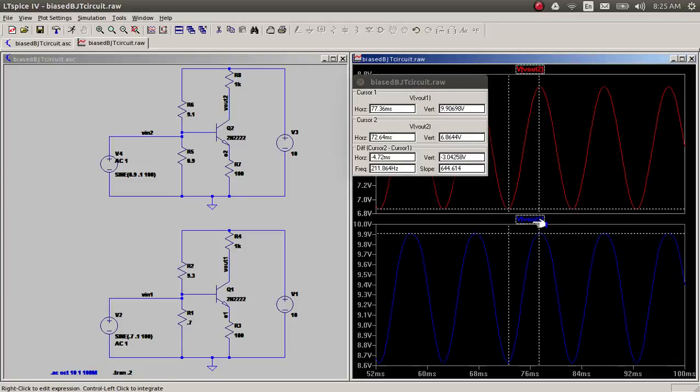And if I look at this one, then this is 1.27, so similar to what we had got before. 0.6 volts is what we are getting at the output for the 60 odd millivolts that we had at the input. So the scaling is fine in both cases, it comes up as 10 each time.